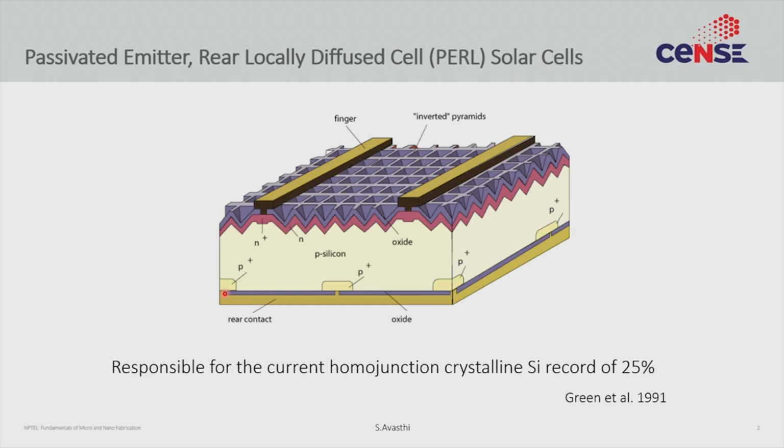So we of course know how to make a PN junction. We of course know how to select a substrate. So we start with the P-type substrate. We can probably diffuse an N-type region. Okay. We would notice that there are two diffusion layers. So there's an N plus layer and an N layer. So there probably is gradation.